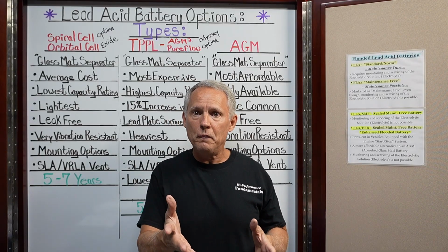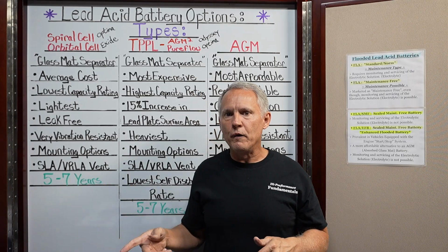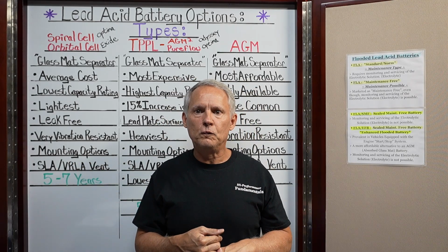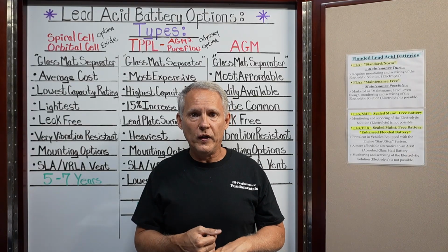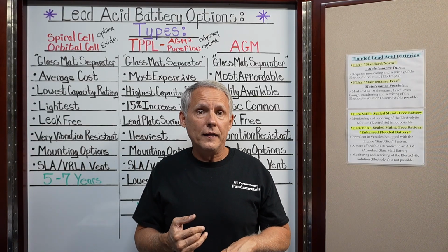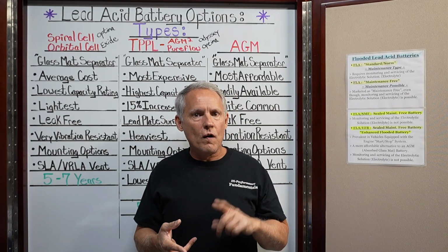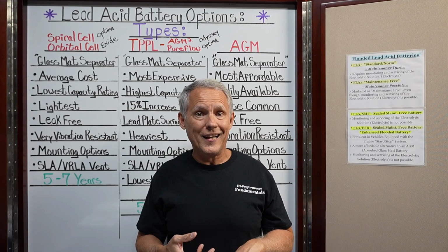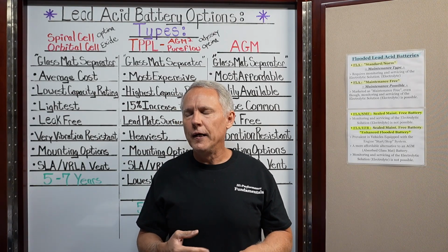A 14 volt battery might be a good option for you, but like I said, there are some things you're going to have to do. But on a 16 volt battery option, if you're going to go that route, then you're going to have to buy the specified battery charger to charge it properly. If you do get an alternator for the vehicle, it's going to have to be an alternator that is designed for 16 volt batteries. And then from there, if you have cutoff voltages of 18 volts or whatever, then you'd better make sure that the voltage from that alternator is regulated down to less than 18 volts at all times, right? Otherwise, you're going to have problems, right?